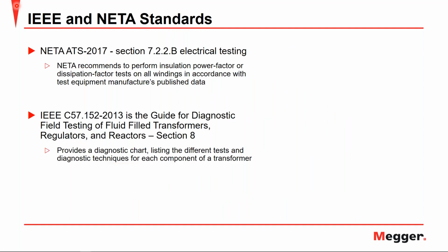And another reason to test power factor is there are international standards, several of them, that also promote power factor testing. For instance, we have the NETA ATS standard here that recommends to perform insulation power factor or dissipation factor tests on all windings in accordance with the test equipment manufacturer's published data.